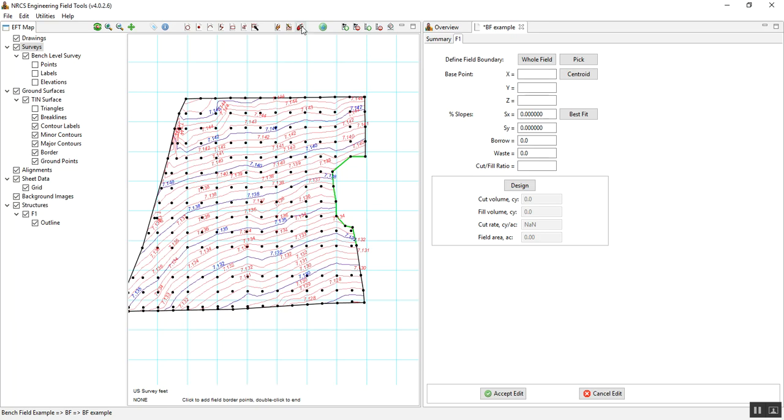And then you're going to click snap to point, and then real quickly I'm going to snap all the points that I want to be within my first field. Once again, I'm just doing this right in half, so you just click every point, and then when you get to the last point, you're going to double click it.